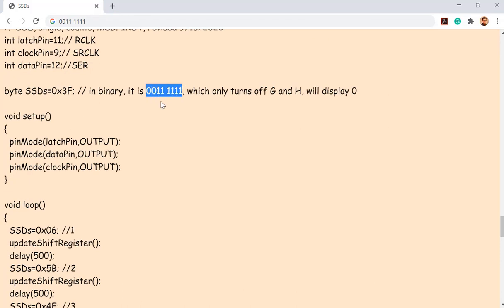Okay, so it's an 8-bit binary number. If I'm using MSB first, it's going to shift the MSB first and then followed by all the other digits. That's important because if you have a number like this and you know it is shifting the MSB first, you can expect what numbers are going to be pumped to the output.